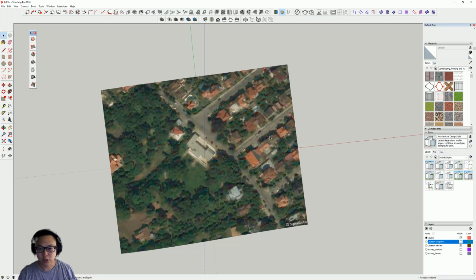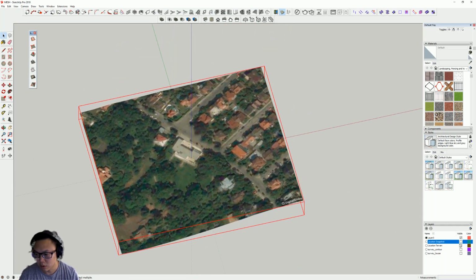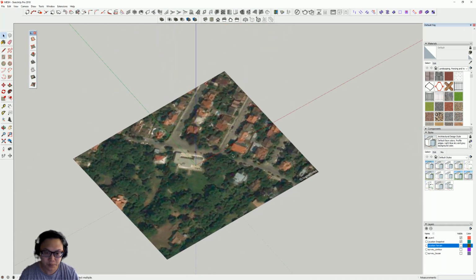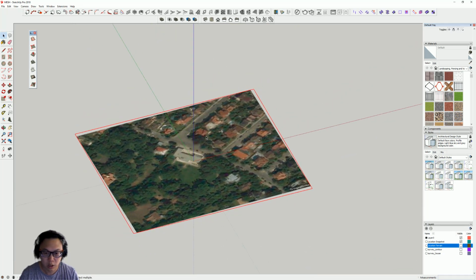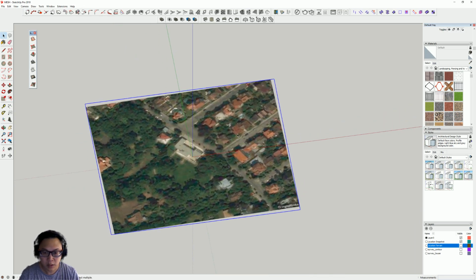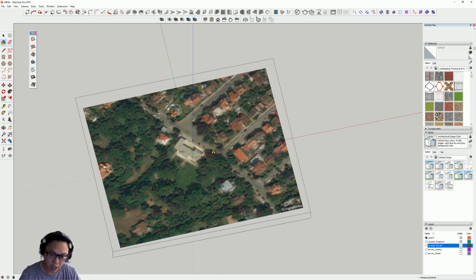So if we go into SketchUp, I'm going to go to the snapshot layers. Look at that, as you can see, it's red. It means that it's locked. Just right click and unlock this layer. Double click to go inside the group, and if you press B, it's the tool to apply surfaces. But if you press Alt, it will, just like in Archicad, absorb the property. And as you can see now, it's under the material palette.